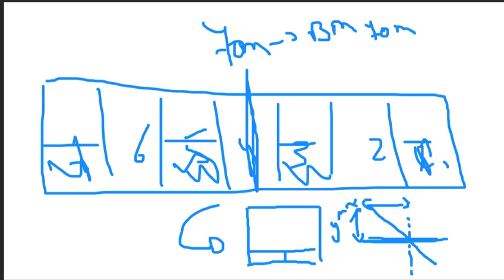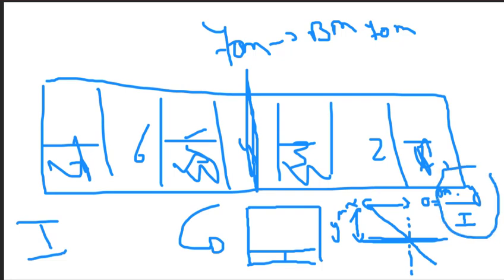You multiply by the bending moment and divide by your resistance against bending to come up with your stresses. So this stress level equals bending moment max at 70 meters multiplied by Y max divided by the moment of inertia, I. We have to fill this in to calculate that value at the weather deck level.